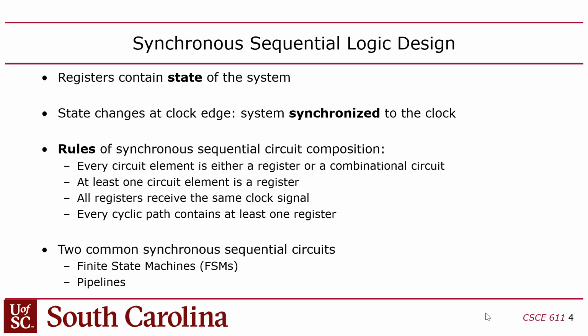Registers, as I mentioned, contain the state, and if you're using flip-flops for your state, then the state will change on the rising or the falling edge of the clock. So when you're designing a synchronous sequential logic circuit, and when I say circuit, by the way, what I really mean is HDL, right? When you're designing the HDL.